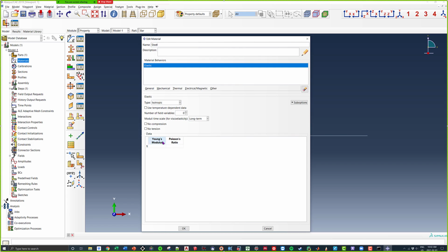The first is the Young's modulus, and the second one is the Poisson's ratio. If we're doing steel, we'll have the Young's modulus as 200,000 MPa. The same thing that we did in Mathematica applies here. Whatever units you have, it's fine. You can use whatever, just make sure that it's consistent. So if I'm doing MPa, then I'm going to be using newtons and millimeters. The second thing is the Poisson's ratio. I can specify a Poisson's ratio, let's say 0.3. Why not? Because it's steel. That's one of the nice things about the finite element method: we start accounting for those things that we neglected before. So we're actually accounting for Poisson's ratio in this case.